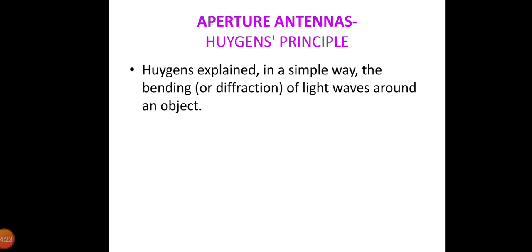In the original problem, the fields that satisfy Maxwell's equations in the region exterior to the volume V, and that satisfy boundary conditions along S, are unique. As long as the source is exterior to V and the boundary conditions along S are not changed, the solution E and H will not change.